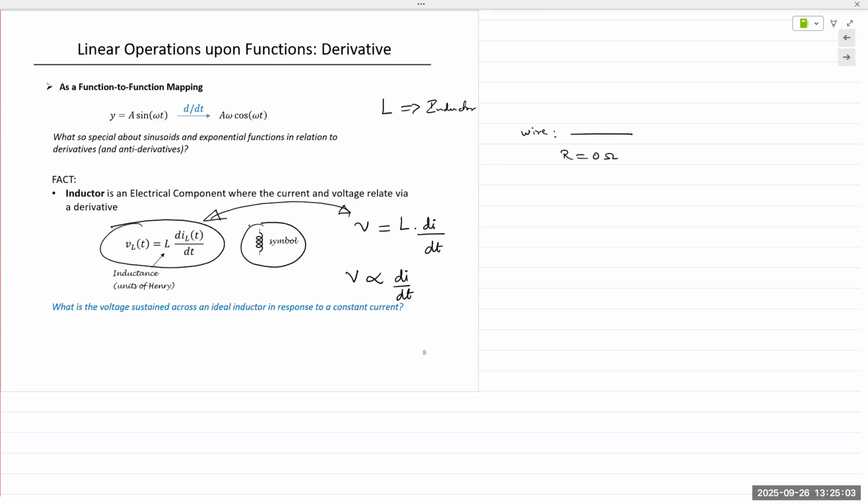If I plug a 100-foot long USB cable into the computer here, and I try to run something 100 feet away, chances are it may or may not work properly. Because on a USB cable, the data signal is probably just a few volts or less. The power line for a USB is 5 volts. So depending on the resistance of that 100-foot USB cable, our data might not transmit properly. The resistance and the inductance and/or the capacitance of the cable might interfere with our signal. There are just some practical considerations to keep in mind.